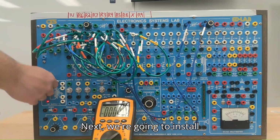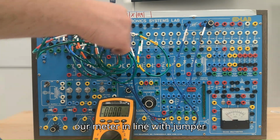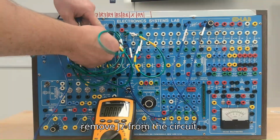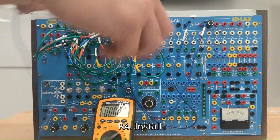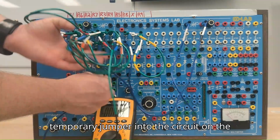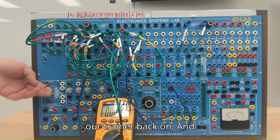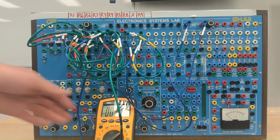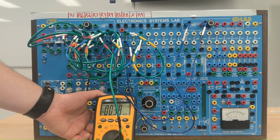Next, we're going to install our meter in line with jumper J7. So we're going to remove J7 from the circuit, which is installed on the bottom side of R4. Install J7 into our meter. Install our temporary jumper into the circuit on the bottom side of R4. Going to turn our trainer back on, and the amperage flowing through jumper 7 is 0.38 milliamps.